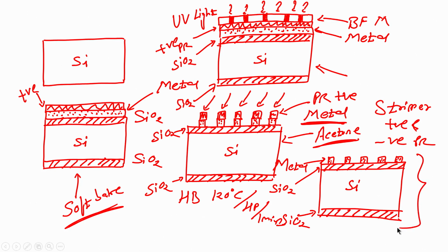I will have an oxidized silicon wafer with patterned metal. Now, before I dip this wafer in metal etchant, I can always do the inspection of the photoresist patterning. So, this is the photolithography technique. I have given one example where you can create interdigital electrodes with the help of photolithography.